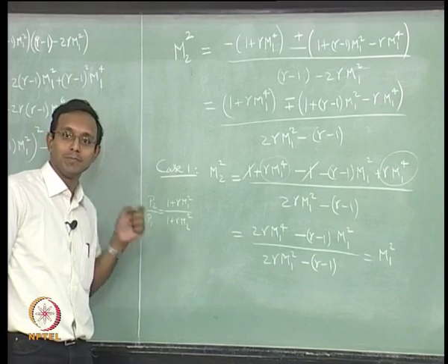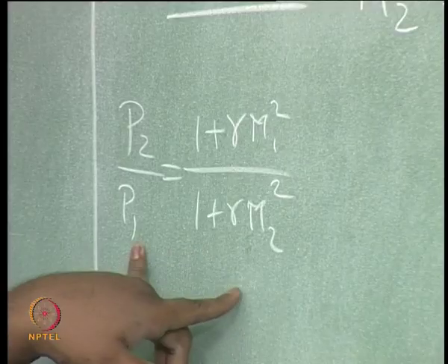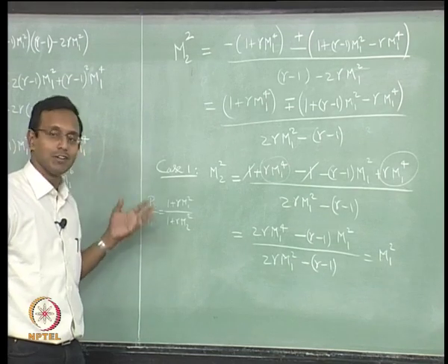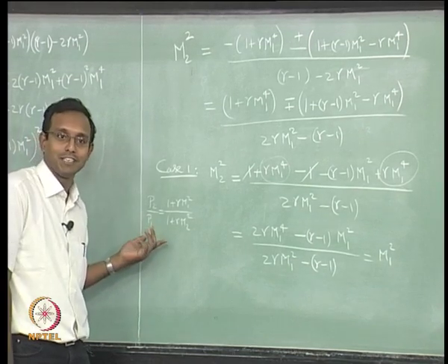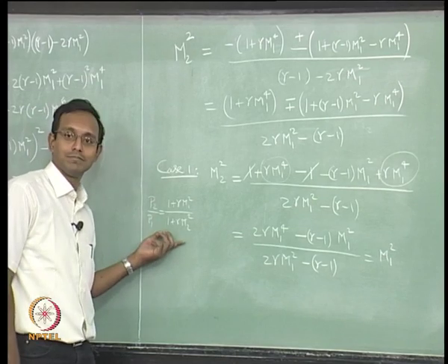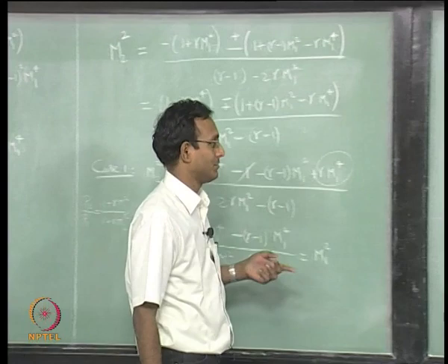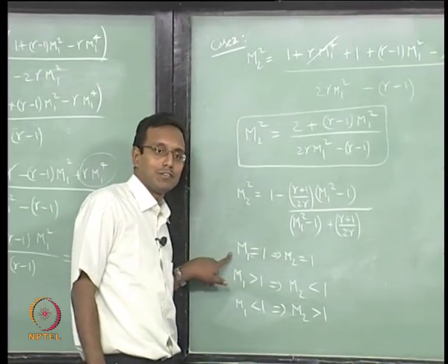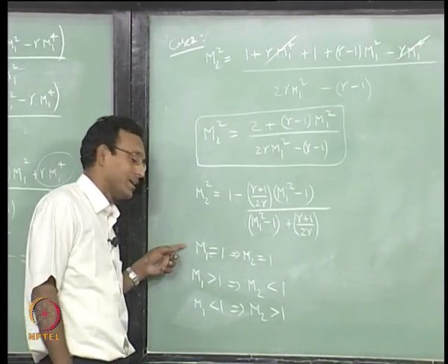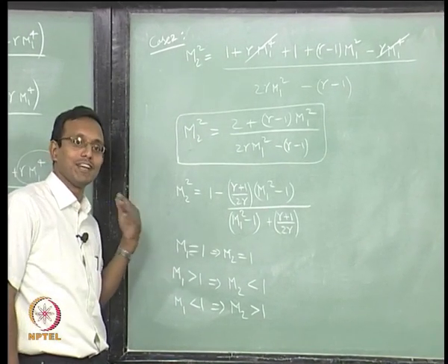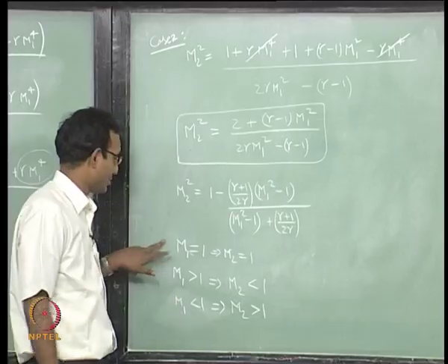That is your simple acoustic wave called your Mach wave. That is also a possible solution, but it is naturally coming out of the expression. I do not need to worry about it anything special, that is just your Mach wave, nothing great, but we have to understand that that is also a possible solution. If I think about that particular solution, it is not doing anything to the flow, it is just an acoustic wave moving at speed of sound at every point.